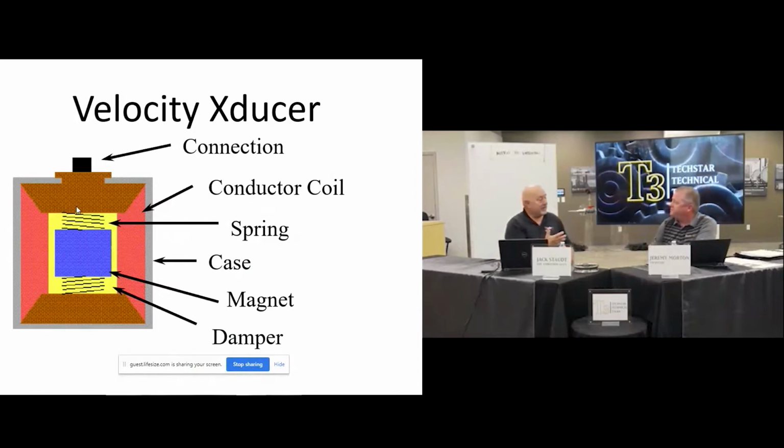And that matters if you're somebody new coming to a system. If you don't know the information, then your data is going to be wrong. But the old velocity transducers, you used to see mainly on gas turbines and things like that. This is what we often call a seismoprobe.